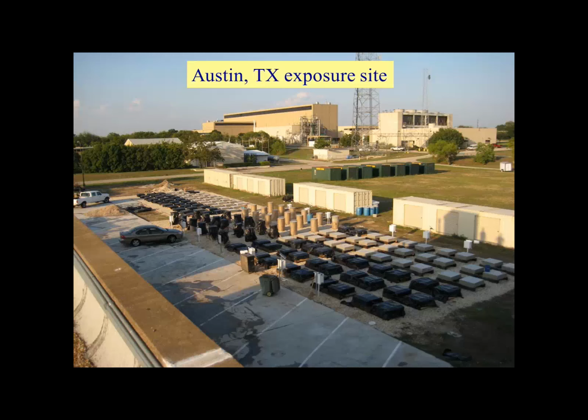That also will vary quite a lot from one aggregate to another. So it means that we may be able to drive lithium in, but that may not be enough with the type of aggregate that you have. So this, I don't think, has been evaluated to enough extent at this stage.